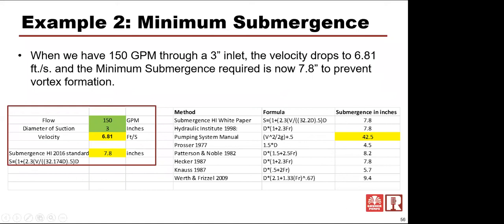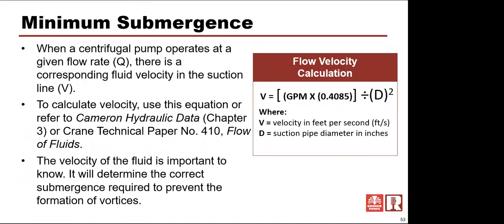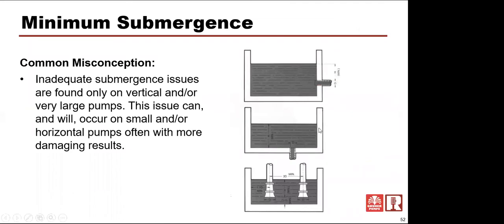Some of the cheats that I mentioned before, if I go back to this particular drawing here, remember it's about velocity here. So we could create a larger opening, larger pipe size, or one of the cheats may be we put a flat sheet across here, maybe a steel sheet that is, let's say, a half circle of, I don't know, 18-inch round half circle.